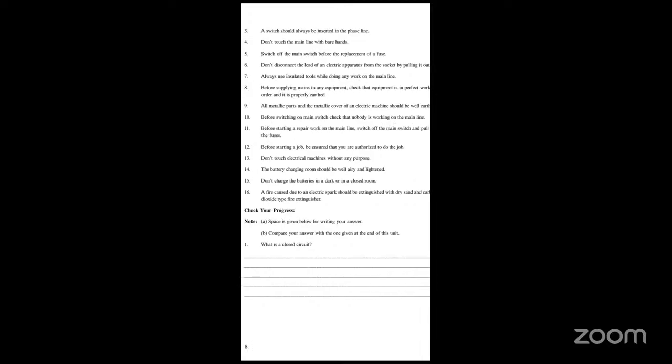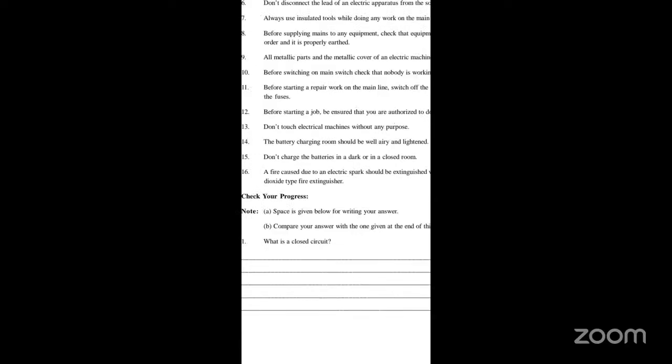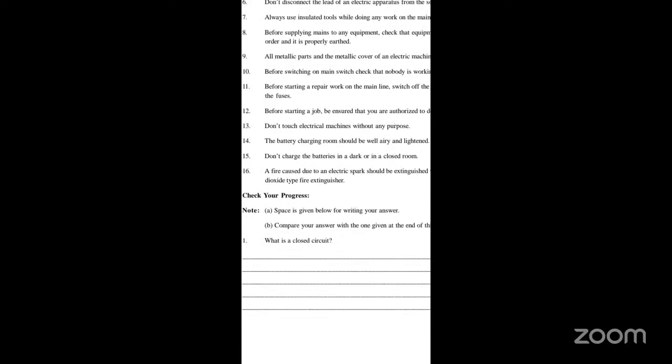Before switching on the main switch, check that nobody is working on the main line. Before starting a repair work on the main line, switch off the main switch and pull the fuses. Before starting the job, be sure that you are authorized to do the job. Don't touch electrical machines without any purpose.